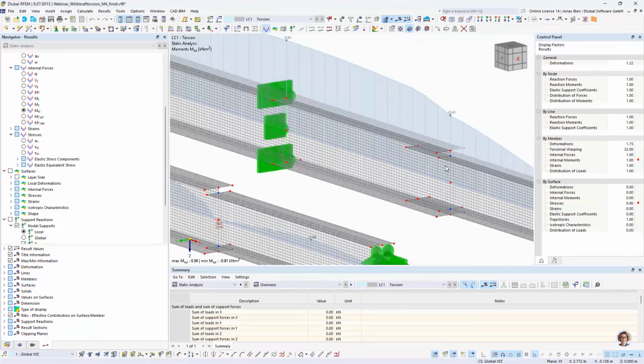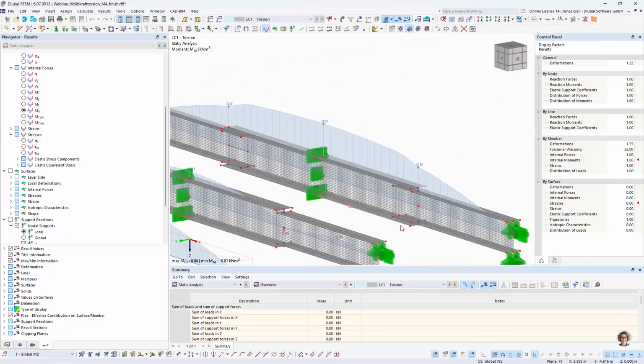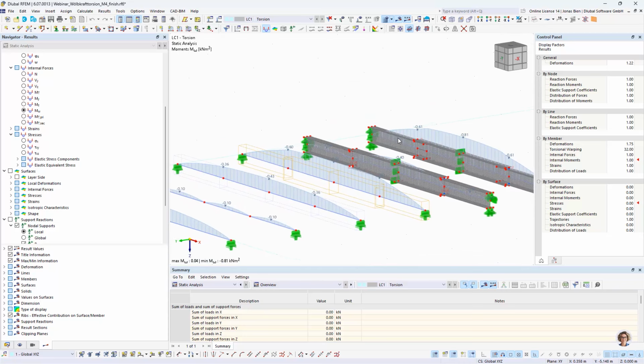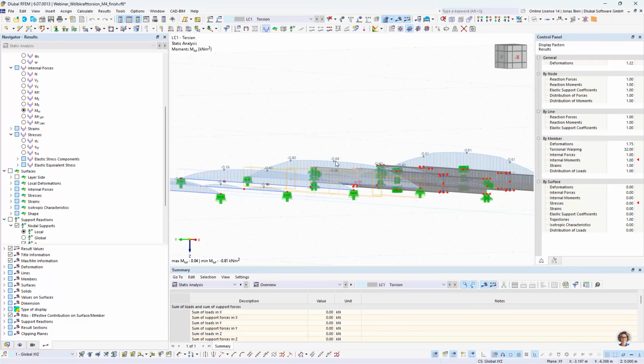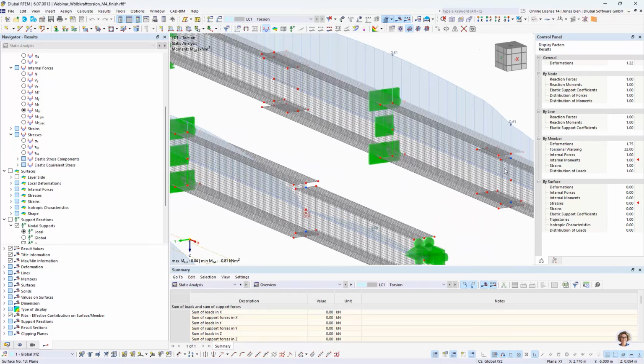And then the third configuration, where we have elongated the flanges of the smaller section into the larger section, we can see that here we have pretty much continuous warping. In this case, we even have a slightly higher warping moment at the middle, because we have a section that has a much higher torsional stiffness, with 4 flanges.